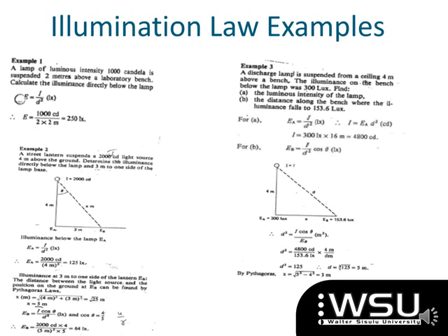But what do we know? We know that we are going to have your illuminance at that point being 153.6. So you go to your formula, E is equal to I over D squared cos theta. Now remember, what is your cos theta in this case?